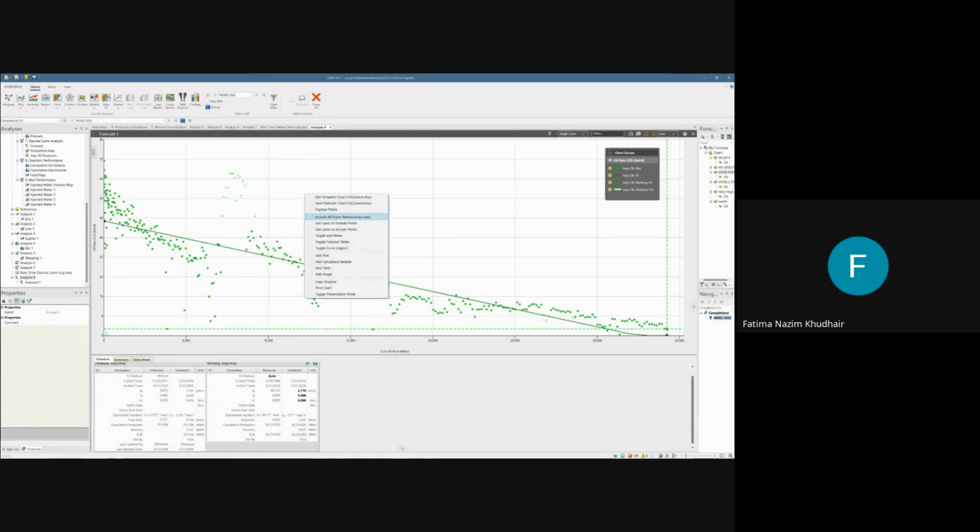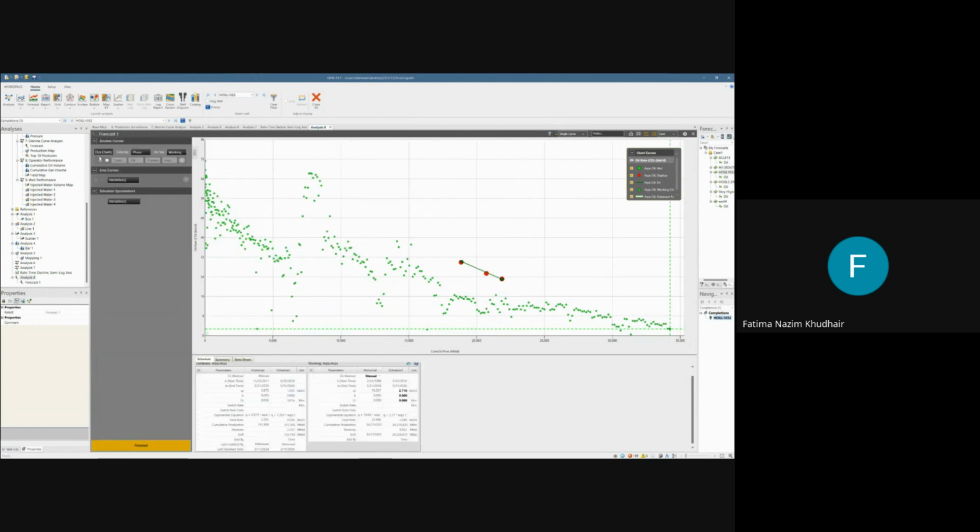Also, in 2023, there is an additional feature, which is the digitized point. This will be points for forecasting that is defined by the user himself. You will draw different points and then right-click again, tell OFM you are done with your points, and look, here is your line for forecasting. This is ARPS2 that I've just created. Oil and gas, in case we are picking more than just one case.